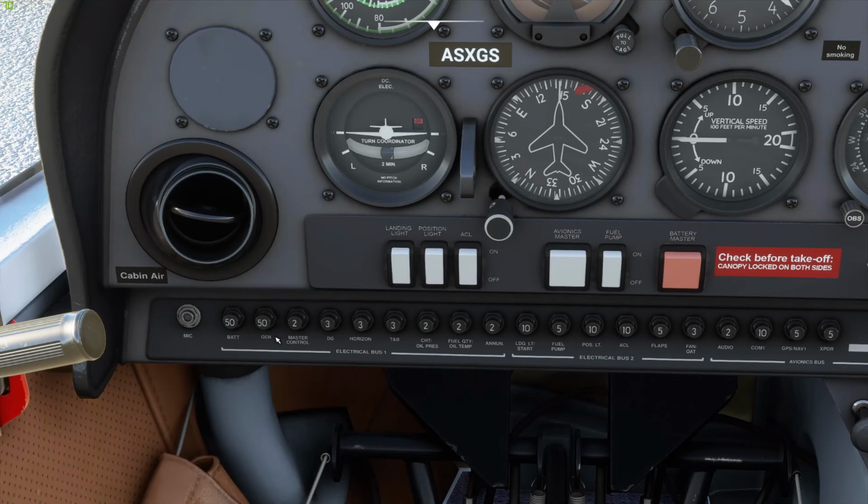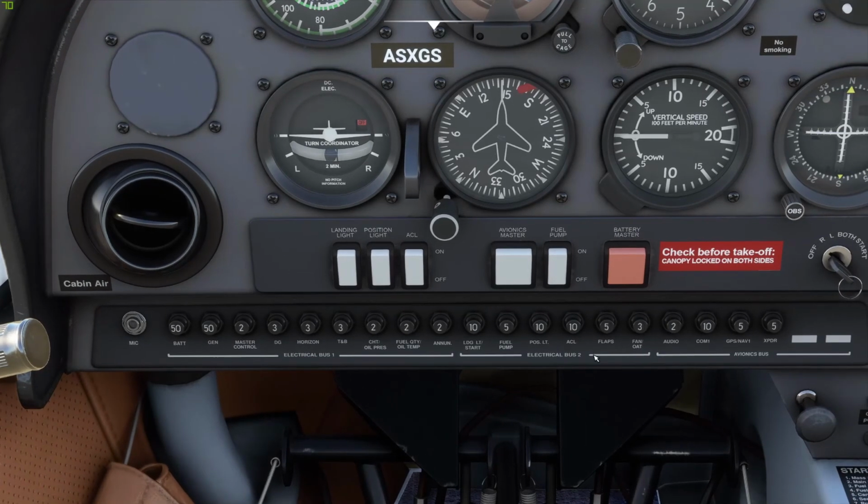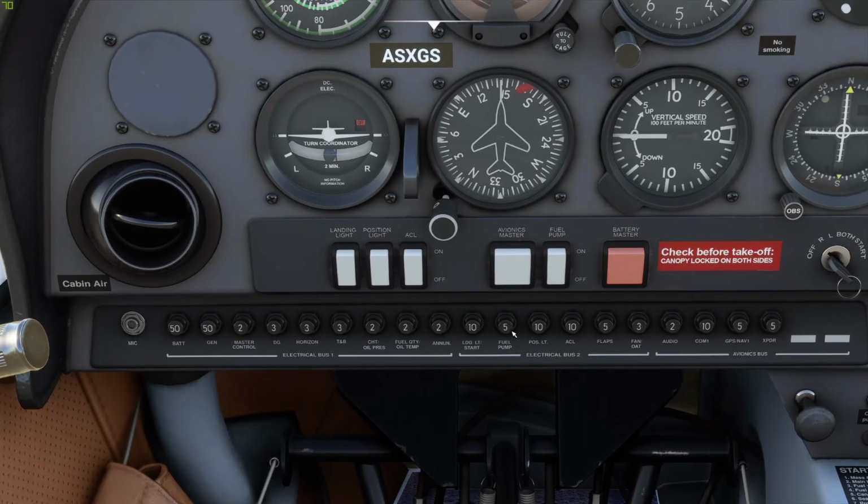So you can see that there's a battery generator, and then the rest is pretty much just instruments with pretty low draw. And so this gives you an idea about all the things drawing electrical power on the airplane, which is quite a lot. Flaps are electrically powered. These are the instruments, the directional gyro and artificial horizon, turn and balance, that's this one. And the fuel gauge, we've got a fuel pump, lights, and starter, which is interesting. It's just on the same one.